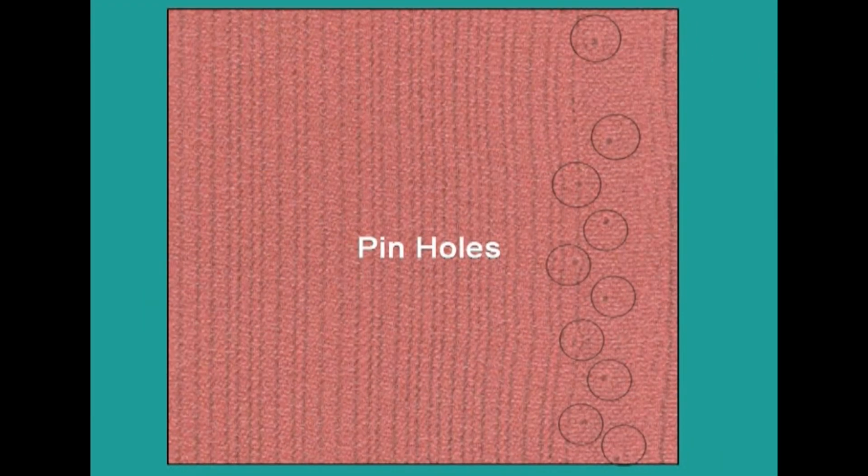And we have another defect called pinholes, and pinholes along the selvage are caused by pins holding the fabric while processing through the tenter frame. It becomes a major defect if pinholes extend into the body of the fabric far enough to be visible in the finished product. Otherwise, most of the fabrics which are tentered will have these pin marks, and that is a pinned frame, and if it is a frame consisting of clips, then you will not have this kind of problem.